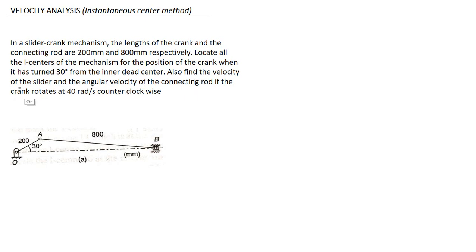Also find the velocity of the slider and the angular velocity of the connecting rod if the crank rotates at 40 radians per second counterclockwise. So hope you have got a basic understanding regarding this velocity analysis by using the instantaneous center method.